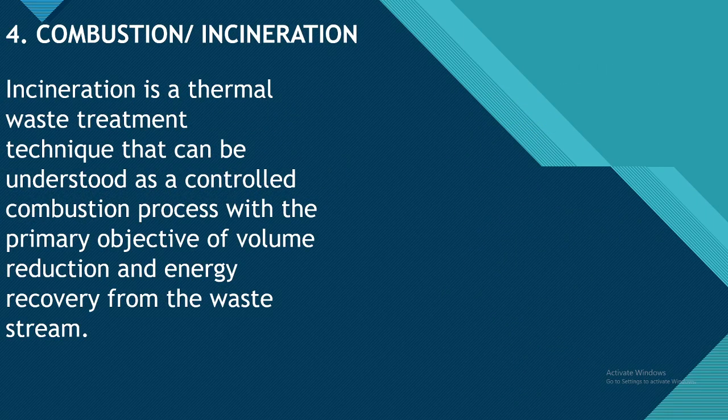The fourth one is combustion and incineration. Incineration is a thermal waste treatment technique that can be understood as a controlled combustion process with the primary objective of volume reduction and energy recovery from the waste stream.